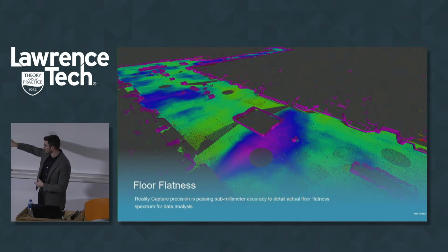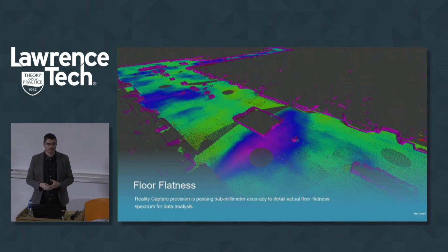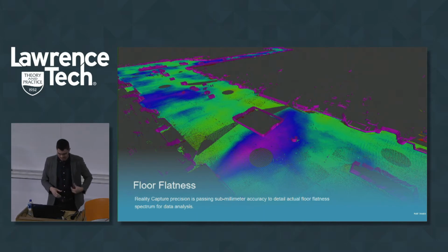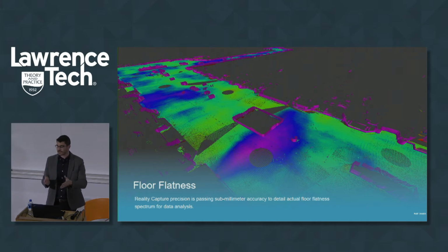And we know that this is gypboard that's got certain paint, it's got a certain texture on it, or different soundproofing has a certain texture on it that we can capture actually with reality capture. So then we get down to what do we actually need to convey, what's important, how am I going to model this, and then formulate this on my plans. Even with a lot of BIM platforms, we take a finished floor elevation and we apply that to the whole floor, that whole level, and we know that's not true as well. So you really have to understand that wherever that finished floor marker is, only that elevation is. You're going to start to deviate 1/100th of a foot, 1/10 of a foot potentially in different areas.